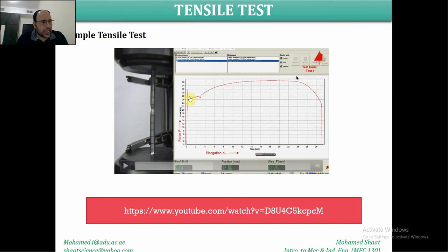There are some mechanical properties related to the plastic behavior of the material that we can derive from the region on the right of the yield region. And there are some other, elastic mechanical properties of the material that we can derive by investigating the line before the yield region. Make sense? So this curve that we end up with is known as the force-elongation curve. Then we can convert this curve into a stress-strain curve later by doing some other calculation. Make sense?